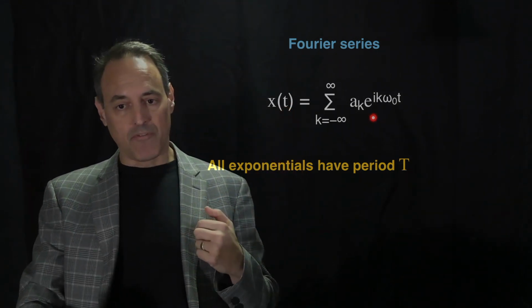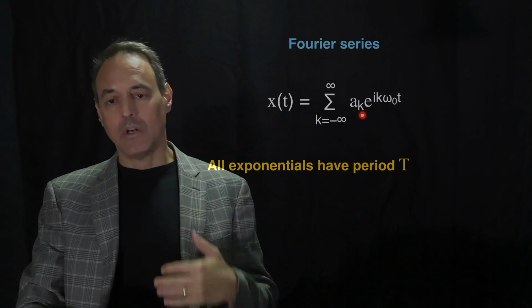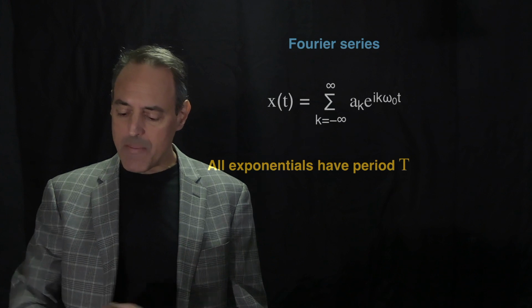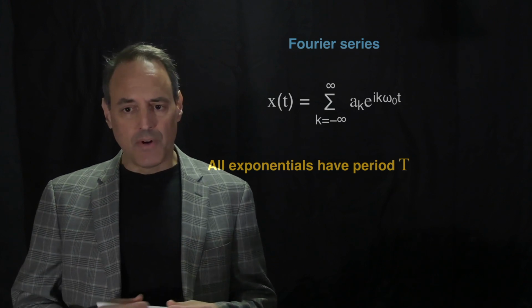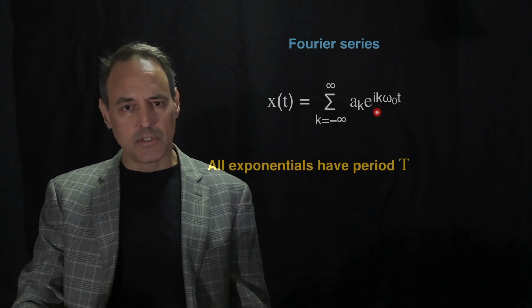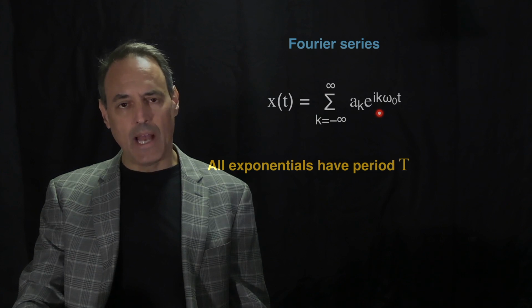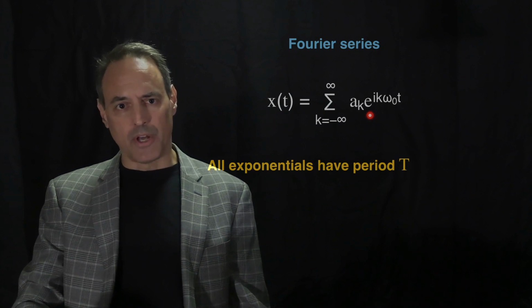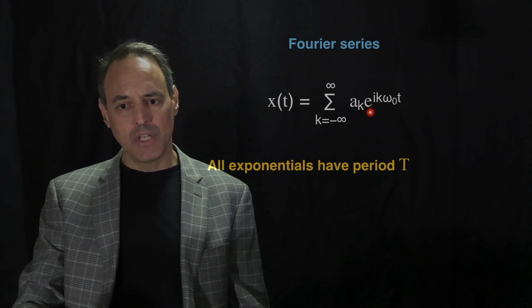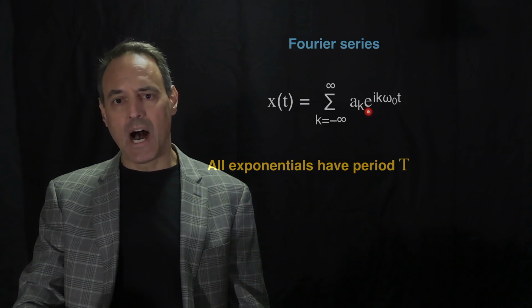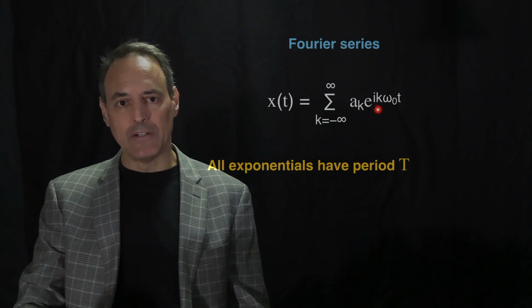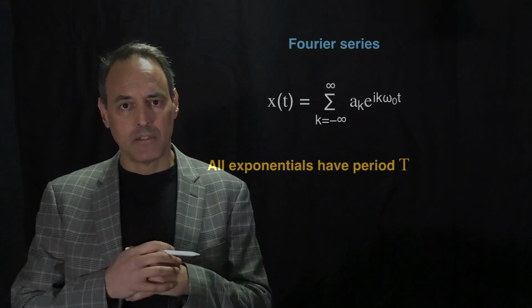these are all my periodic functions that if I add them together, I'm going to be able to construct any generic solution. The other thing I want to say about these functions, which we're going to start seeing later, is that they are actually orthogonal to each other. Each one of these functions, e^(i k omega naught t), is orthogonal to e^(i p omega naught t), where k and p are different. So each different k value, when we take an inner product, gives 0.